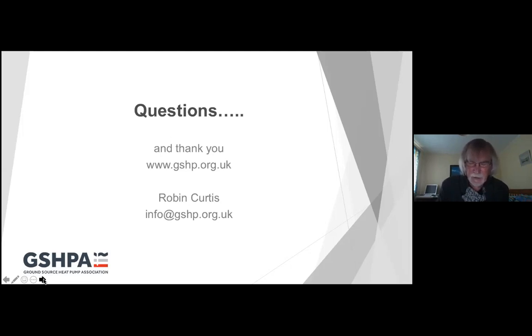Sorry, Laura, just going back a bit. On the domestic side, where heat pumps are being supplied with onboard pumps, someone needs to be taking care of what ground loop they're fitting to that. You can't make the assumption that any old ground loop fitted to that onboard pump will have low parasitic energy. But if you follow the guidelines in the design documents and give yourself a design target of a few percent of electrical consumption in the circulating pumps, a few percent of the compressor power, then you should be in good shape.